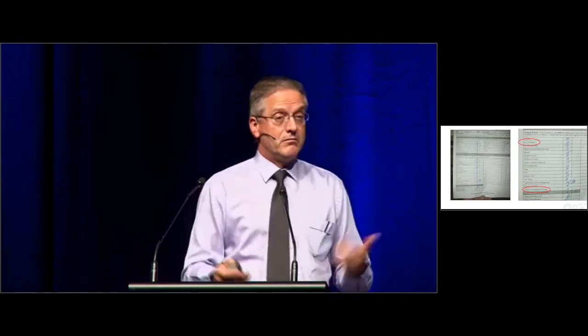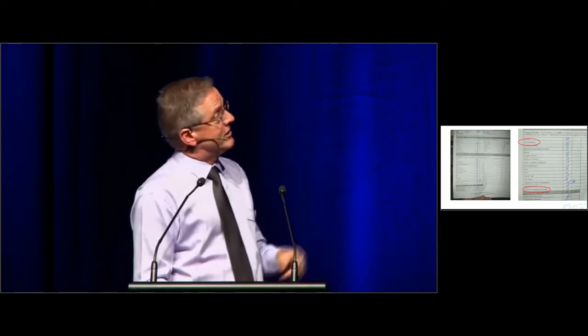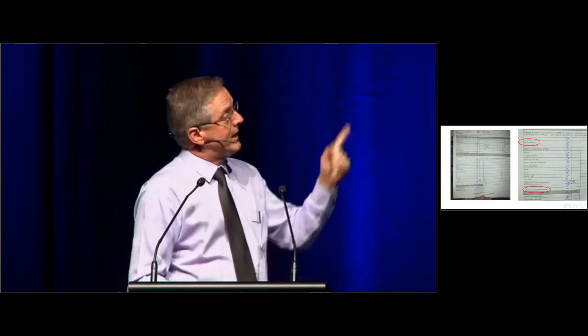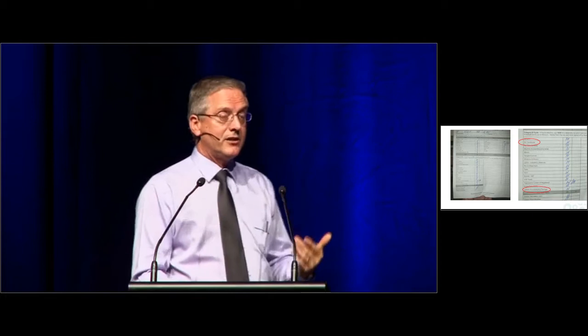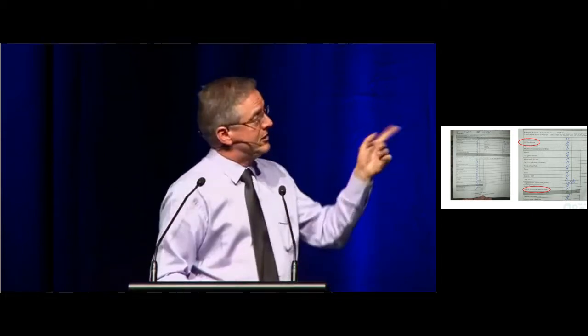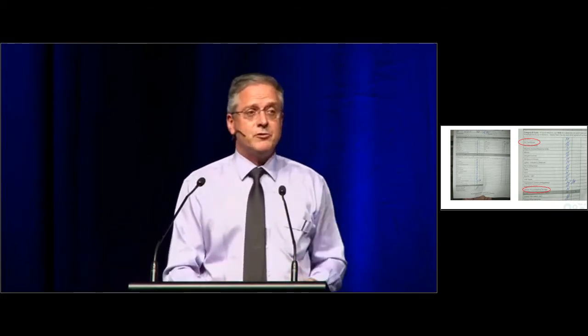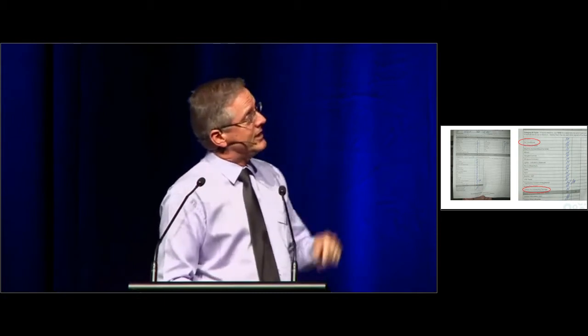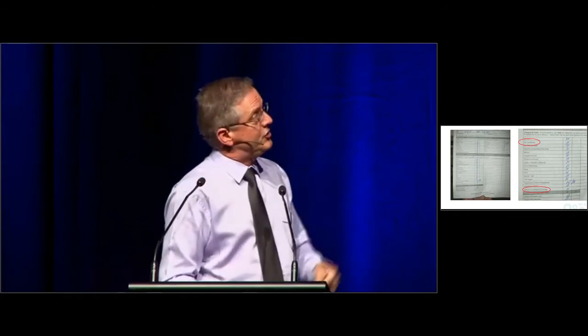That's an example of your normal mobile plant pre-start checklist, and you can see there's a tick box for air conditioning, but that's just whether it works, whether it makes a noise when you turn it on. And the only other one that goes close to looking at the condition of the cabin or the door seals is this one down the bottom. The H is not a high, medium or low, that's Henry's initial. He puts H for Henry in there when he has a look at it. So you can see if an operator is looking, if we're going to get operators to look at something, we have to actually prompt them to look at it properly. And there should be more detail about what the worker's looking for.